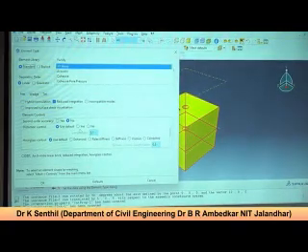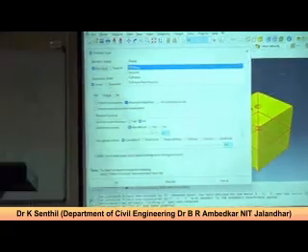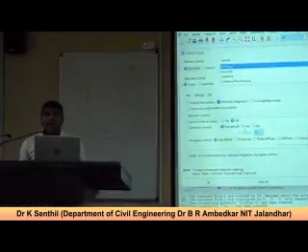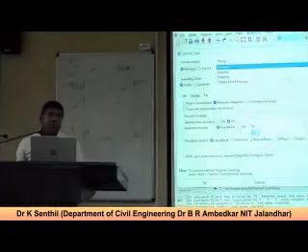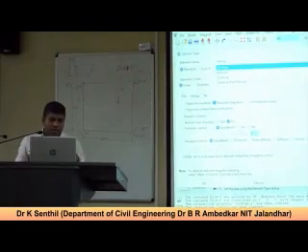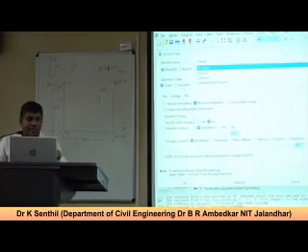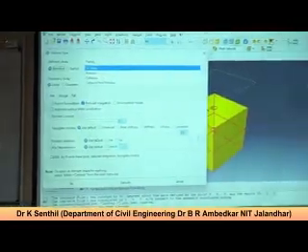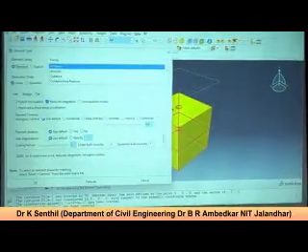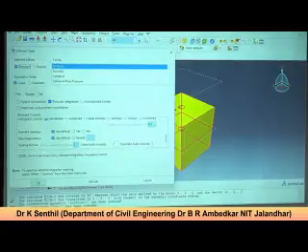That's why that is called a mesh convergence study. It's a very important numerical analysis. Whichever software you use, either Plaxis or Ansys, Abaqus, mesh convergence is very important and you have to take care of it. And also you can adjust the results by varying these inputs like distortion control, hourglass control, element deletions, maximum degradation, all this. So that's fine.